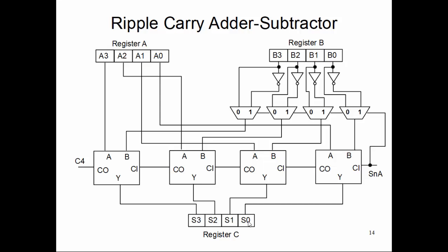Now the next challenge is this: we are looking at a little more complex circuitry here, especially the selection circuit. If you think of this multiplexer, what does it have inside? It has one little 1x2 decoder, then it has the AND gates of selection logic and an OR gate and so on and so forth. You can probably also use some enable circuit in it. So we are talking about a lot of gates needed as we are using a multiplexer in this circuit. The challenge is, can we simplify it?